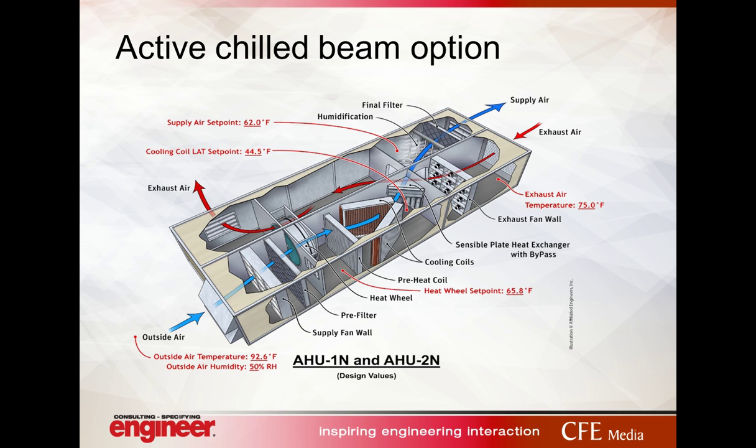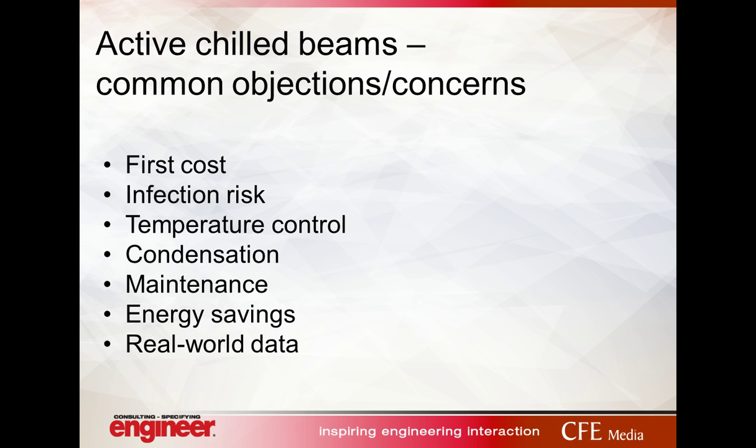The other thing of note here is that in a traditional VAV system, we'd probably send the air out to the space at 52 degrees and saturated or something near that. In this system, we're able to send the air warmer and drier, which is another source of the energy efficiency of this system. Healthcare is a conservative industry for all the right reasons. They're taking care of patients first and every other consideration is second. So when new technologies come out or new systems get evaluated, there's resistance, and they're responsible to do that.